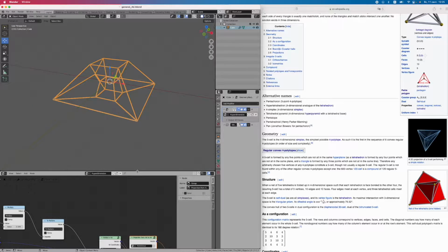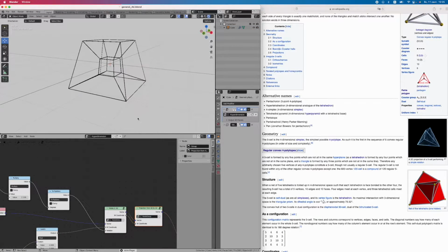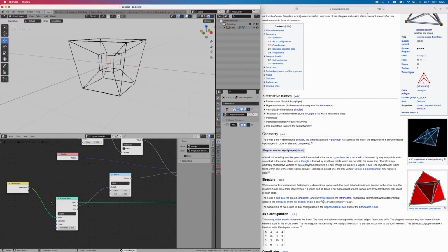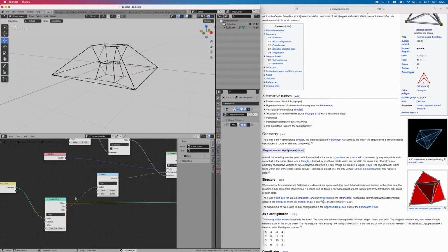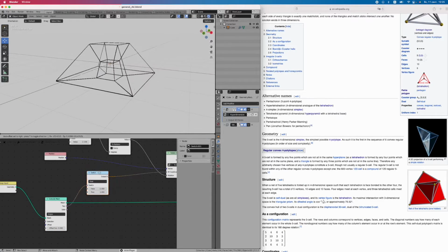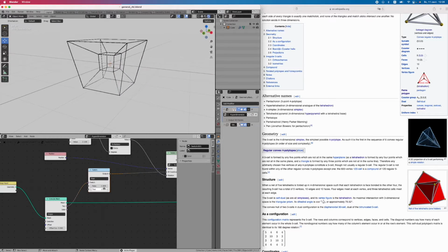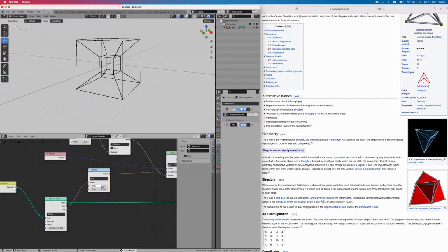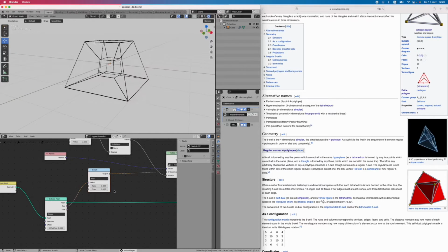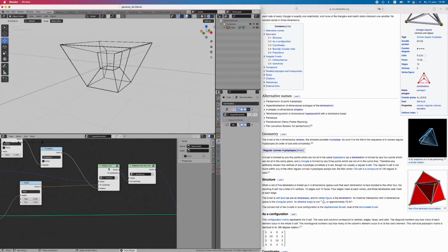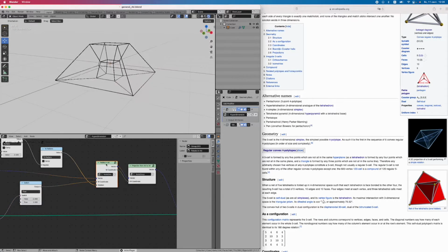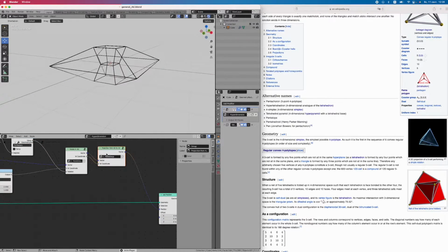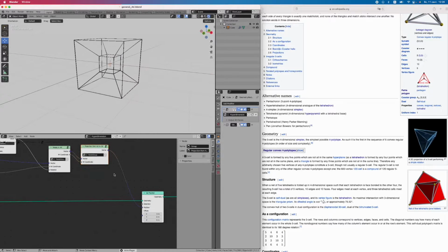So I will remind you how we made the object in the first video. Here, in geometry nodes, I have a 3-dimensional input. With this node I extrude this whole object into the 4th dimension. With this switch I apply coordinates to this 4th dimension. So some vertices exist on -1 on the 4th axis and some on +1. And then I apply my custom node rotation in 4D, and then apply a projection from 4D to 3D. In the first video I've shown how to make them.